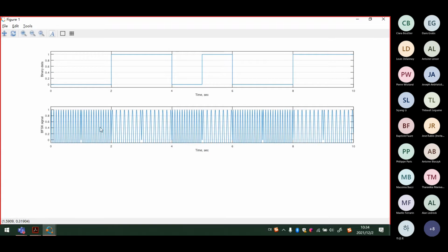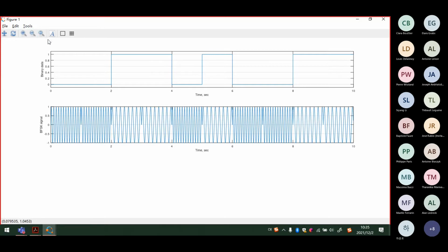And you will see here the k influences the different frequency, and it's more obvious. For the 0 it has a higher frequency, and for the 1 data it has a lower frequency, but you will see here it still has some phase difference, where different frequencies have different phases.